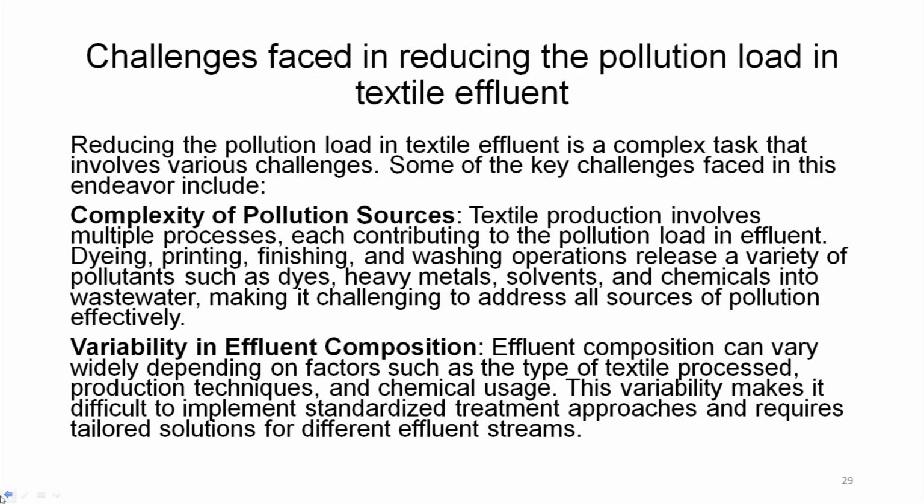The textile production involves multiple processes, each contributing to pollution load in effluent: dyeing, printing, desizing, sizing, curing, mercerizing, singeing, and then we have the finishing and washing operations release a variety of pollutants which include dyes, heavy metals, surfactants, emulsifiers, solvents and other auxiliary chemicals into the wastewater, making it challenging to address all sources of pollution effectively.